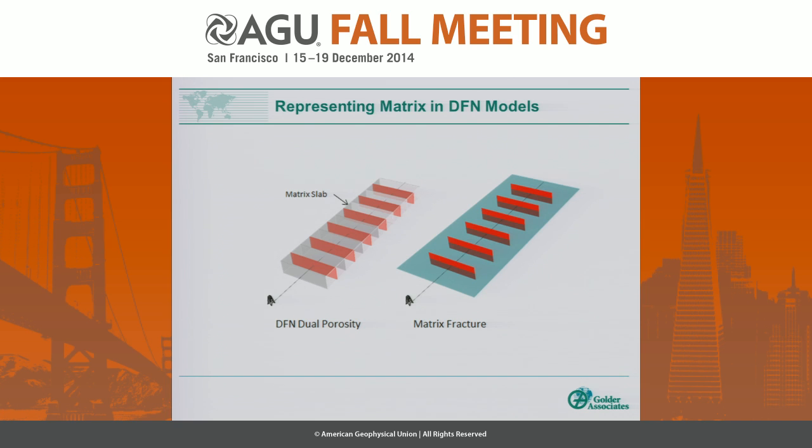This is something where we can have a relatively large, coarse discretization of the fracture, and the matrix slab is a 1D solution associated with the fracture that we can very finely discretize. It's very numerically efficient. However, it only does a certain constant spaced slab. It doesn't account for fracture complexities and possible overlaps.